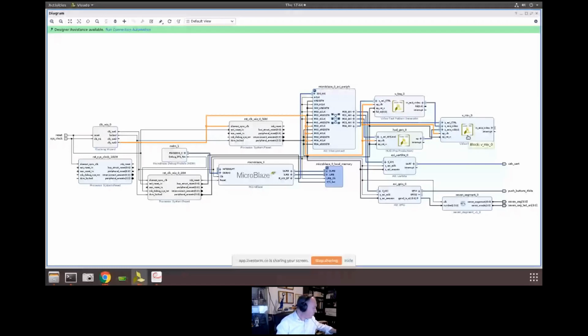What we need to do now, though, is we need an output path. We need to be able to display on the VGA output signal. We need to display on the VGA outputs. And the VGA output on the Basys board is quite straightforward. It uses a simple resistor divider to create the color. So we're just going to use the 4 colors.